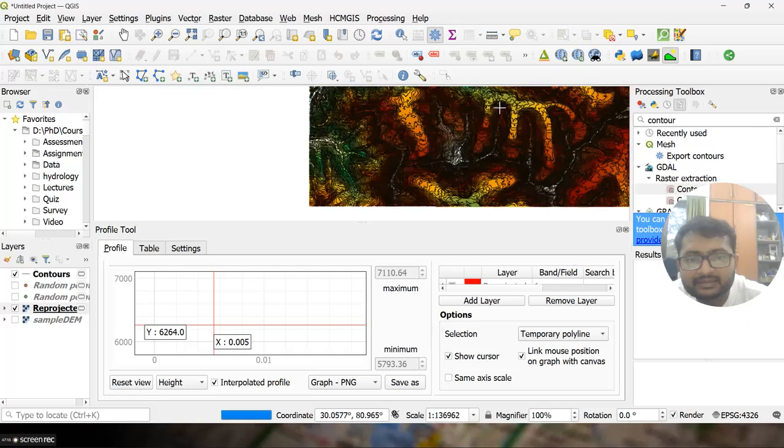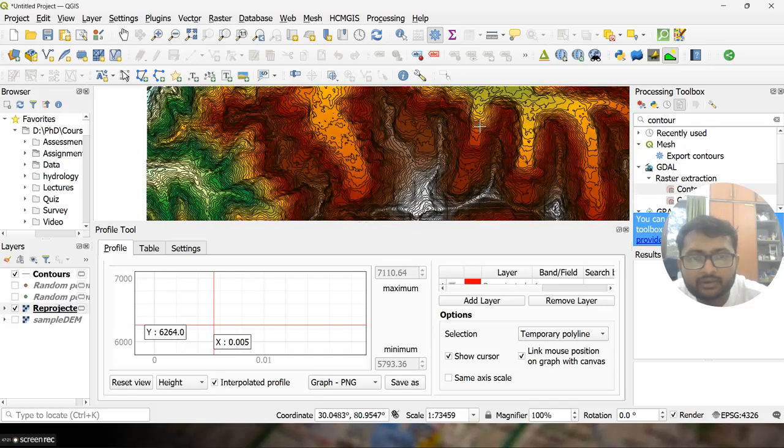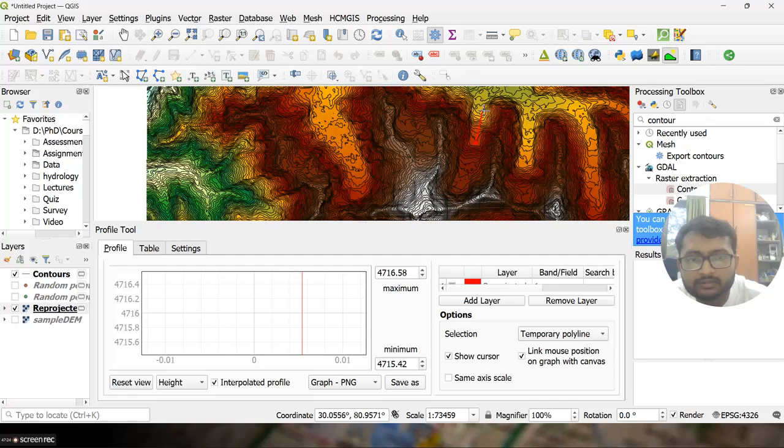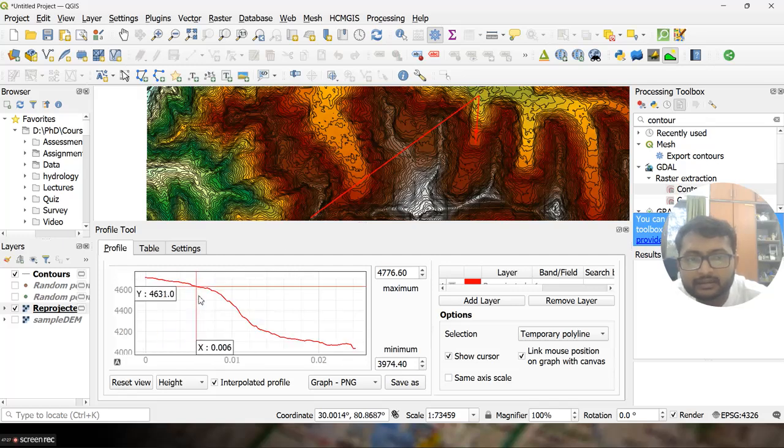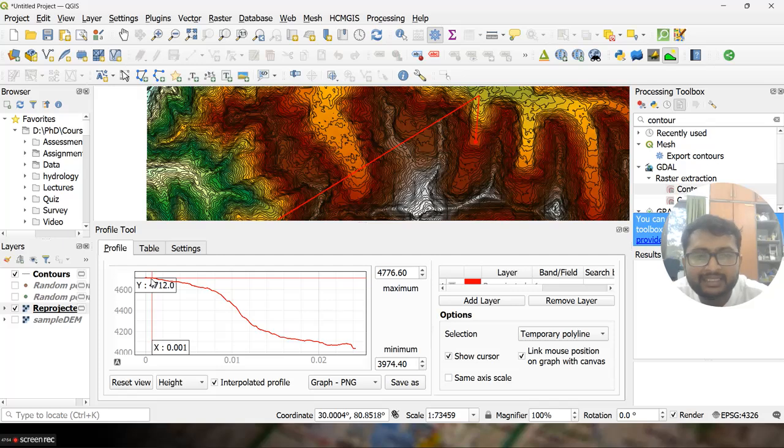And similarly now if I look for, let's say, a valley, then you can see it's a valley. So it's going like this. You are going from this to this area. Here the V or U shape is higher towards the higher elevation areas. So in case of a valley, it is towards the uphill area, whereas in case of a ridge, it is towards the downhill area. So if the point is a valley, if it is going down, then top elevation. If it is a ridge, which is a top elevation, then it is towards the lower elevation.